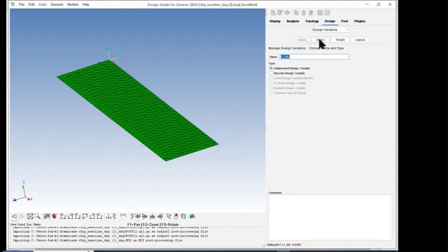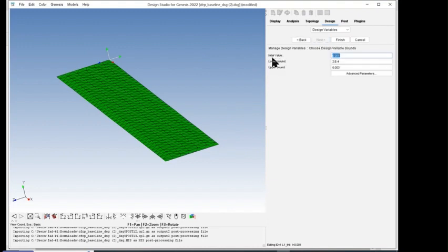If we click on next and examine that, we can see we had an initial value of 1, a lower bound of 0.2 millimeters, and an upper bound of 3 millimeters. So what we said was initially it's 1 mil, that layer, but it can go down to 0.2 millimeters, 1 ply, or it can go up to 3 millimeters, 15 plies. And it can have any number between those 2 limits. Okay, and that's why we came up with that value of 1 1/4 ply for that variable. It's theoretically possible, or it is possible between the limits that we've set, but it's not manufacturable.